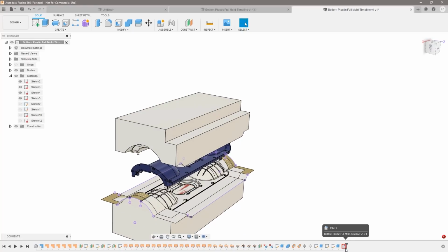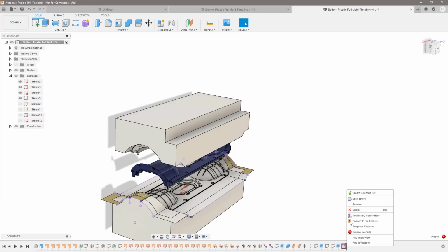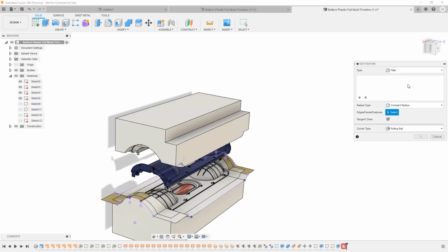Now, this one here gives us a red because there's literally no chance for it to display. Before, when the sketch was broken, Fusion could still solve it. But in this case here, it cannot. It's missing literally that area. And again, if you don't fix these, then that's going to be broken, and you will never remember where they were broken, right?